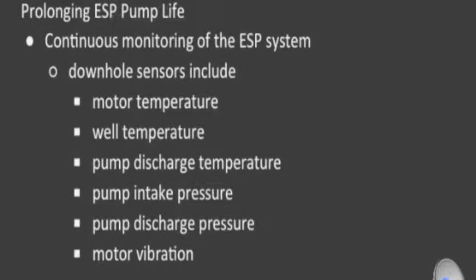ESP life is being prolonged through continuous monitoring of ESP systems. Some of these new downhole sensors include motor temperature sensors, well temperature sensors, pump discharge temperature sensors, pump intake pressure sensors, pump discharge pressure sensors, and motor vibration sensors.